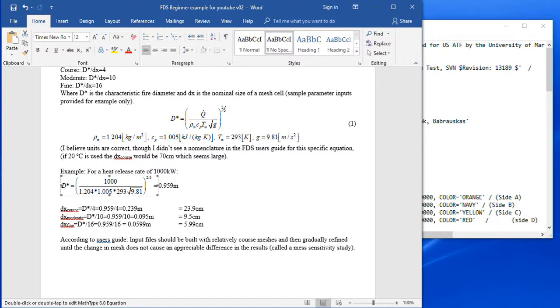Now, before I made this video, I was trying to find a reference in the user's guide that says the input temperature is in Kelvin. Since this is heat transfer, it should be an absolute temperature scale, but almost all of the other temperature references in the user's guide are in Celsius.